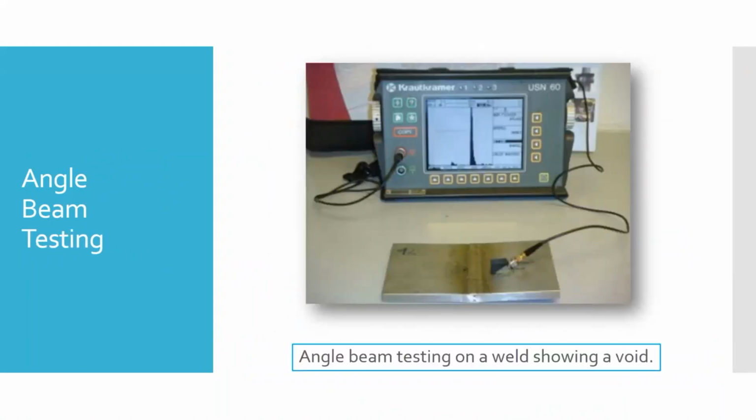So here's where angle beam testing is often used. You can see in this case, you can't go directly on top of the weld, because it's not a smooth surface. You wouldn't be able to get a good acoustic bond between a reflection probe and this. So they're going along.